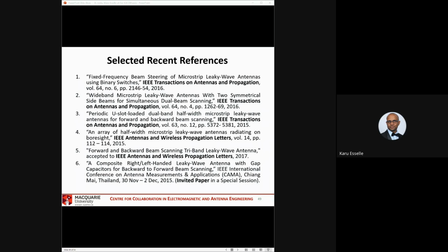I don't know any other antenna that has so many names. Resonant cavity antennas are also known as electromagnetic bandgap resonator antennas or EBG resonator antennas, Fabry-Perot resonator antennas or Fabry-Perot cavity resonator antennas, partial reflector surface PRS antennas, and also 2D leaky wave antennas. I think at the end of these few lectures, you will understand why they are called EBG resonator, Fabry-Perot, PRS.